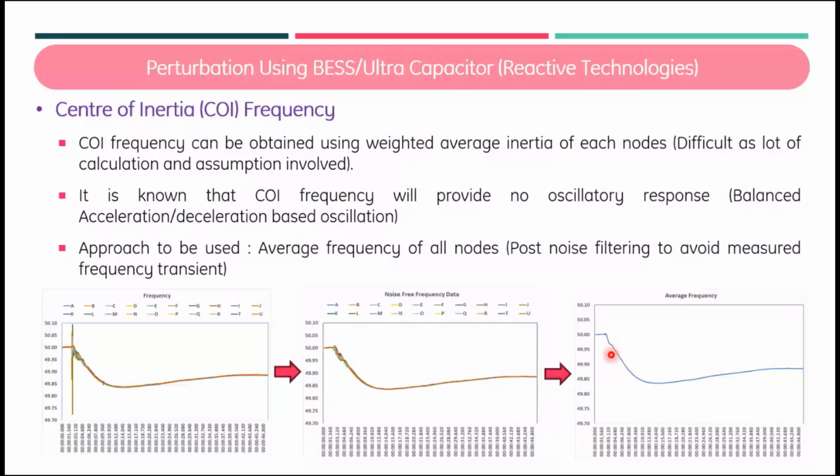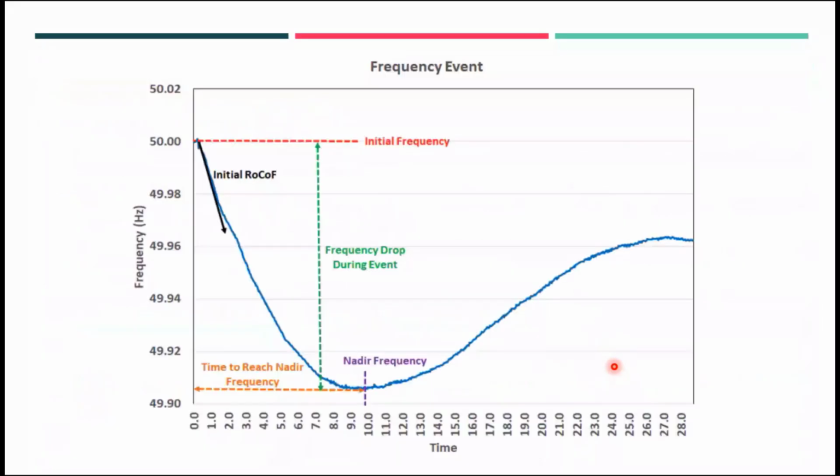So this is the way you can utilize PMU data distributed in a uniform way across the entire power system. You can utilize those data for computation of your inertia using an offline method also. It is basically the disturbance based method using the PMUs.